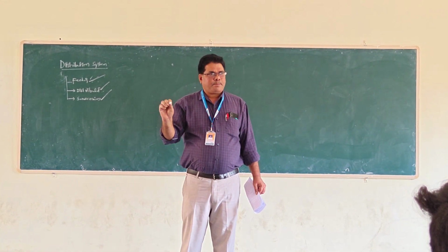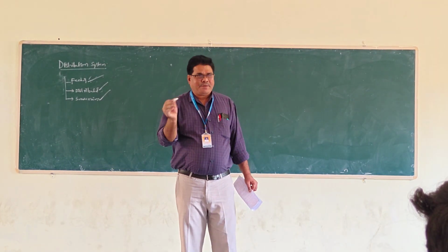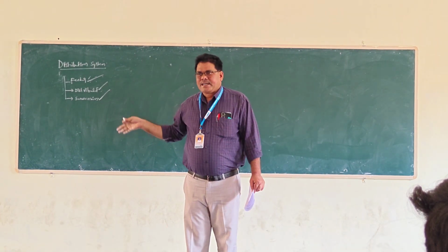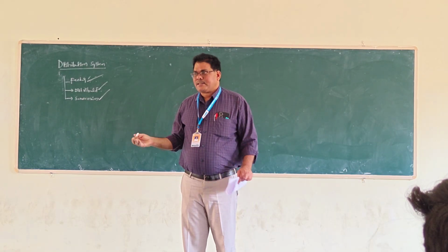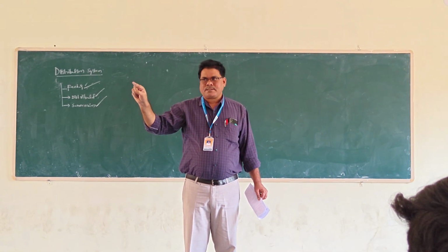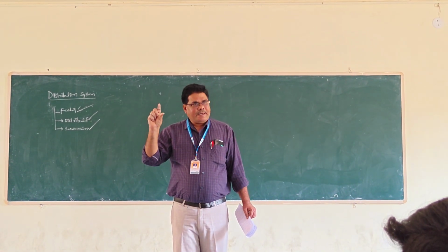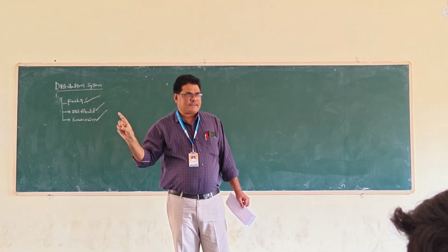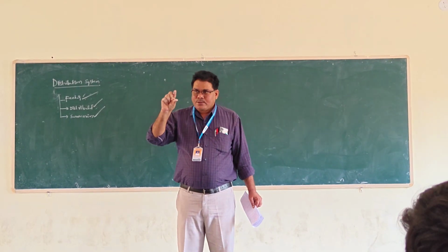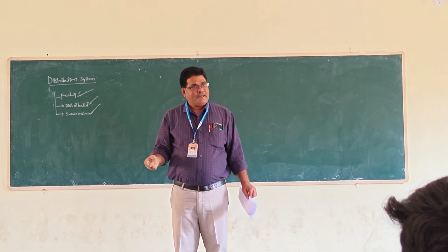These three are conductors, but there is a difference. Feeder is a main line, no tapping, current remains the same, so while designing the feeder, current carrying capacity is the main consideration. Distributor is also a conductor, but it distributes the power to various streets.